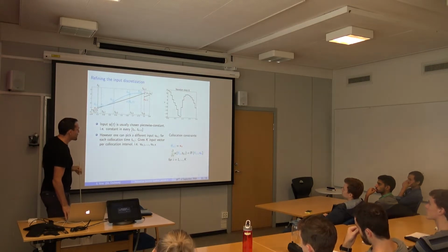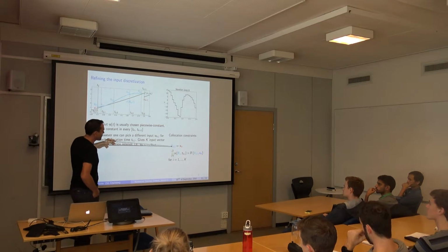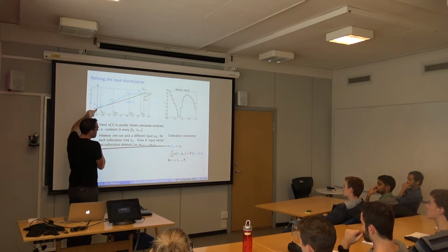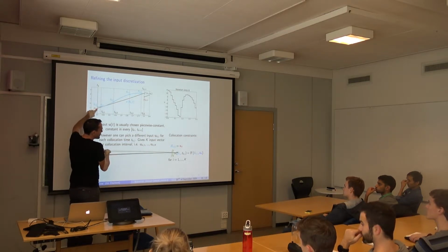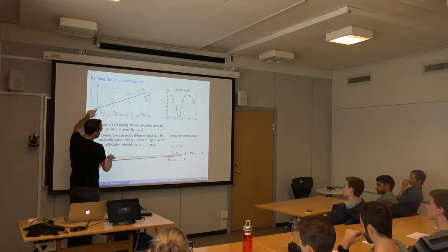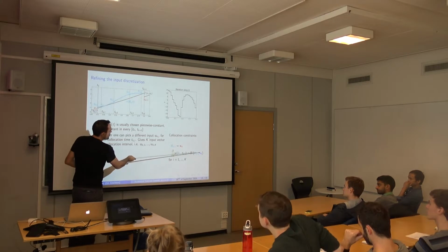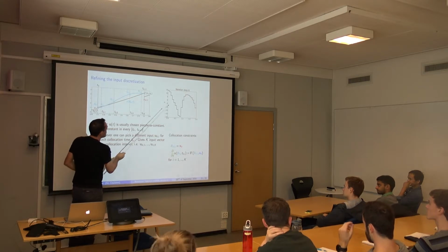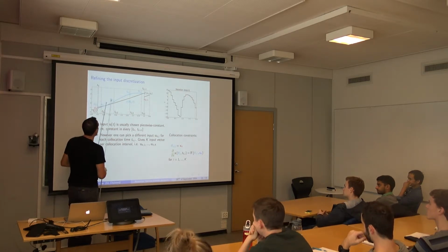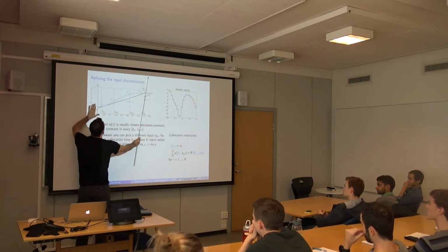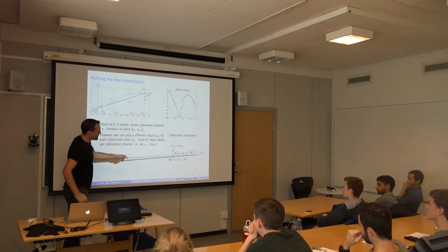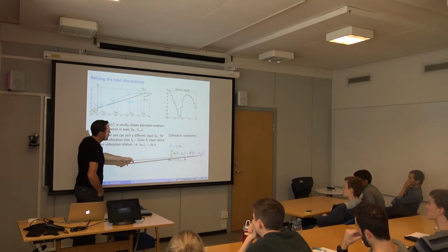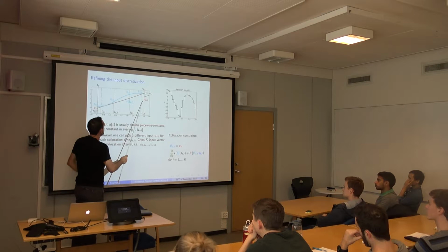That's actually something you can easily spot in the constraints themselves. So if you think of your collocation constraints, you have the one that essentially assigns the theta to the initial conditions on the interval. And then we had the constraints satisfying the ODE on the other time points. And u_k is piecewise constant, so it's constant on this interval to t_{k+1}. But if you were to have a polynomial for the input u in that interval, where you would place it in these equations would be essentially by saying my inputs in the interval k can also change for these different times.